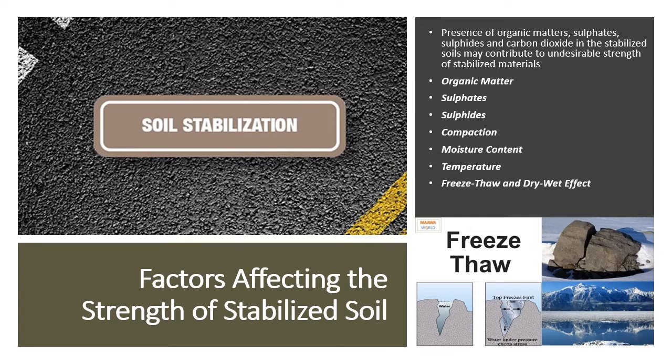The fourth factor is compaction. Stabilized mixture has lower maximum dry density than that of unstabilized soil for a given degree of compaction. The optimum moisture content increases with increasing binders.